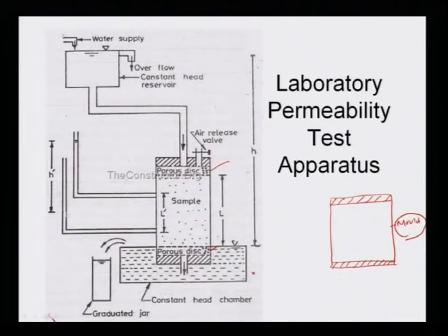So this is the mold, inside this mold your soil sample is there, and with this soil sample it is connected by means of a piezometer. So you can find out how much hydraulic head is developed, H prime. Then here there is a graduated jar, from where you collect your water.